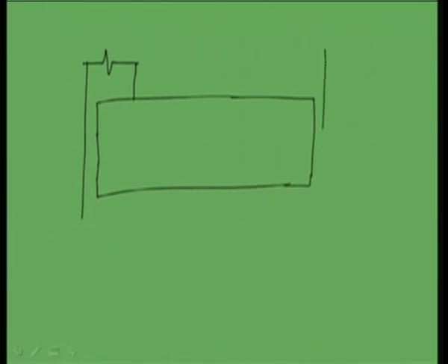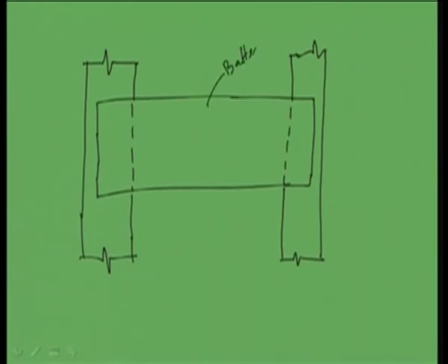So, this is one main member, this is the batten plate, and another main member is here. These two main compression members are tied together through the batten plate. Now, this has been welded. This is the overall depth of the batten plate, and the thickness is D, the thickness of the batten plate. Now, welding has been done, say, in this way.